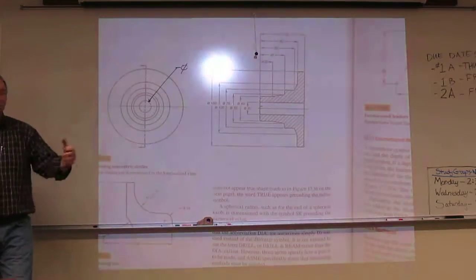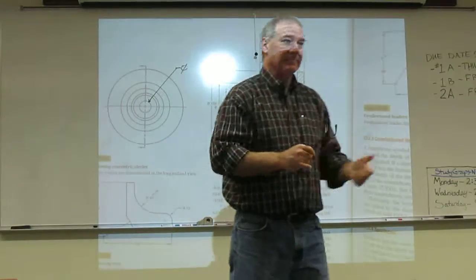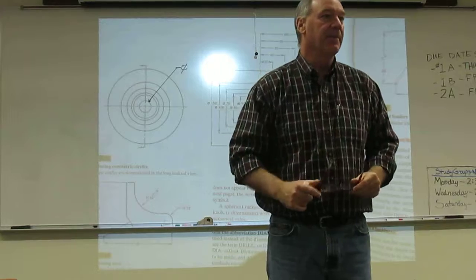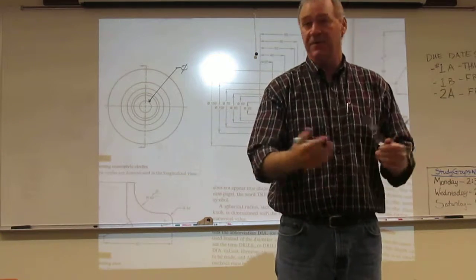And this is a cue to our readers also. They see one done in the circular view, they should know that's a negative cylinder. If they see it done in the rectangular view and it's not a section, they should know it's a positive cylinder.